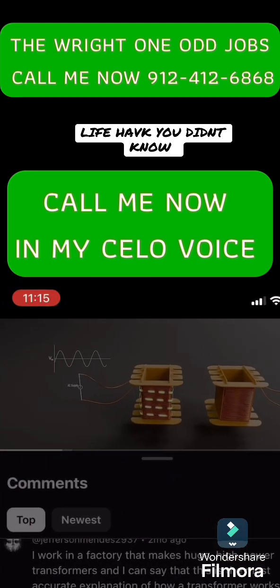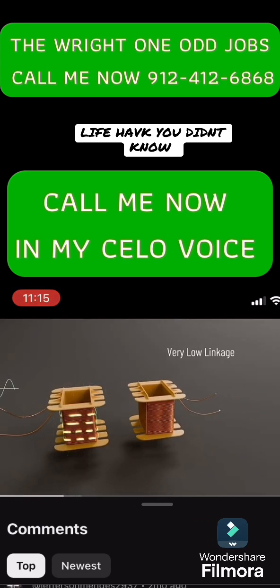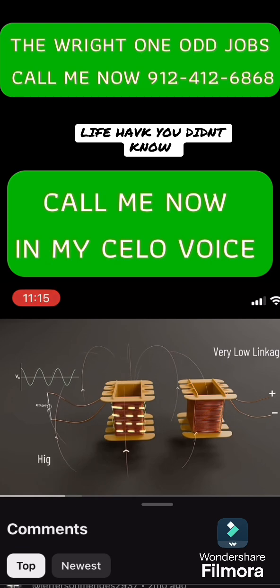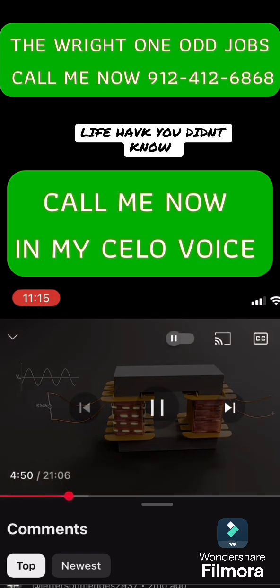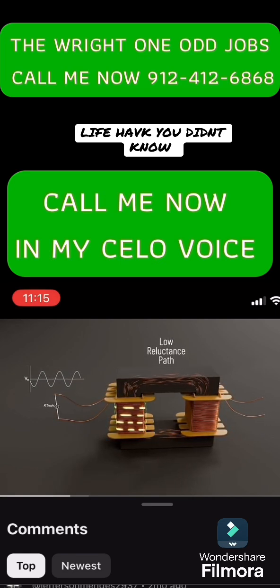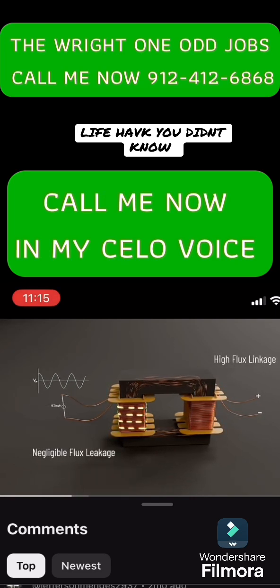The flux produced by the primary winding, which links with the secondary winding, is called linkage flux, while the flux produced by the primary winding, but not linking with the secondary winding, is called leakage flux. It's important to note that leakage flux does not contribute to the transfer of electrical energy, and therefore should be minimized to improve the efficiency of a transformer. A transformer core acts as a pathway for magnetic flux, providing a low-reluctance path. As a result, most of the magnetic flux produced by the primary coil links with the secondary coil, making the transfer of electrical energy more efficient.